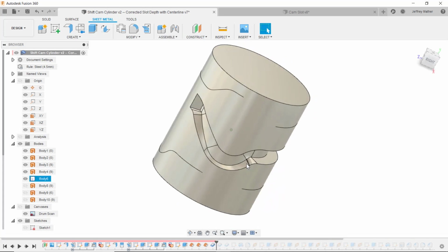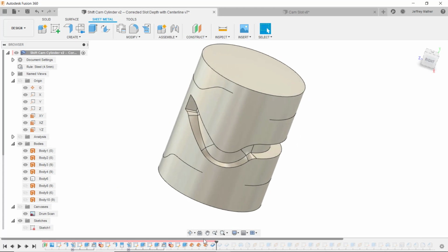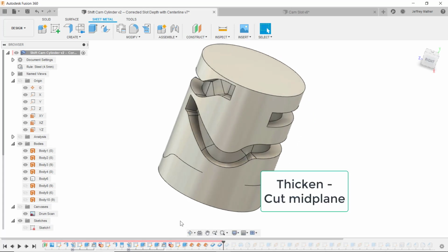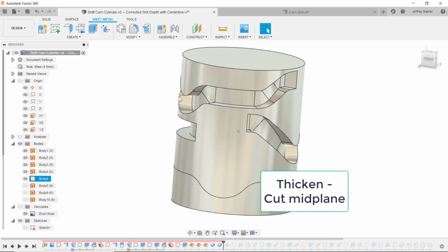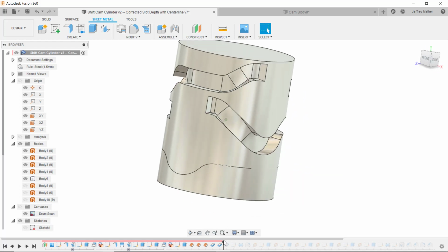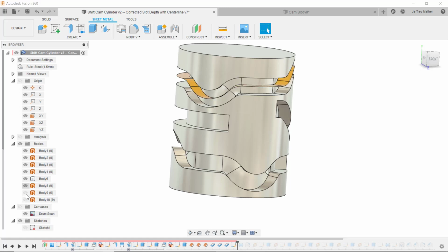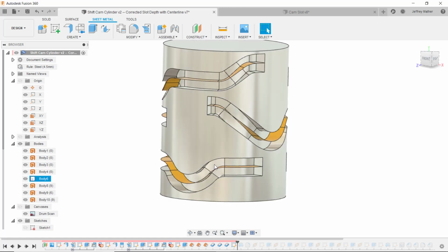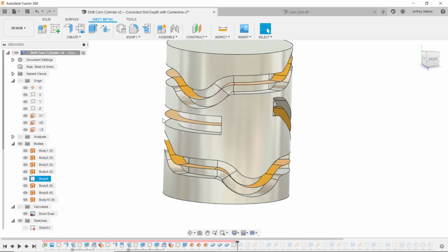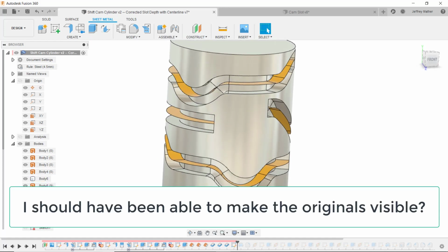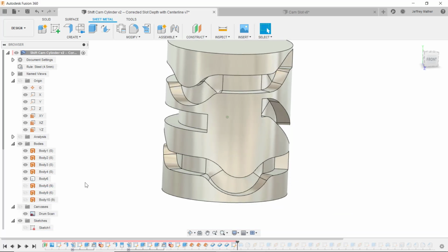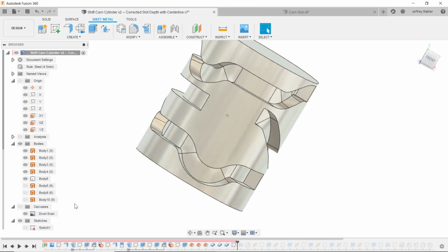And then I extrude cut one of those surfaces, this surface, and then I do thicken. That's the key. You do thicken mid-plane, the thickness of your slot. For machining purposes, you're going to want this curve right here to define the path of your cutting tool, and so that's why I put these copied offset surfaces at distance 0 in here, so that those could be used later when generating CNC code in the CAM.